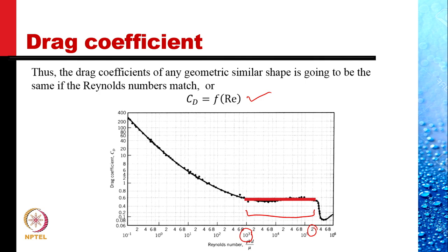So we measure the drag at a much lower speed, convert it into a drag coefficient, and then using the fact that the drag coefficient is independent of Reynolds number, we say that the same drag coefficient would apply to the prototype automobile, and from this we calculate the drag on the prototype.